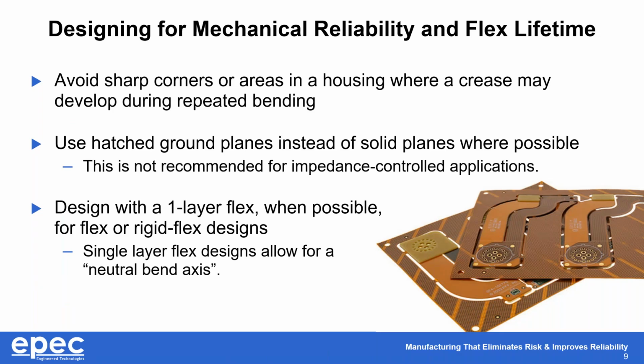This will seem a little contradictory, because there are opportunities where you have to use solid planes, things like impedance controlled applications or shielding. It's just something to keep in mind whenever designing a board. If you have impedance control or shielding, it's solid. If you have neither of those, use hatched ground planes, and it'll at least buy you a little bit of flexibility.